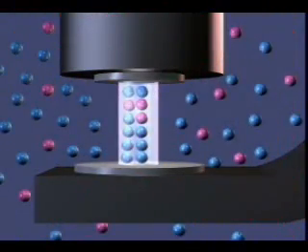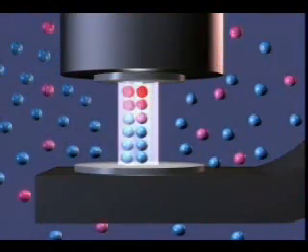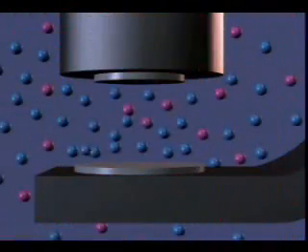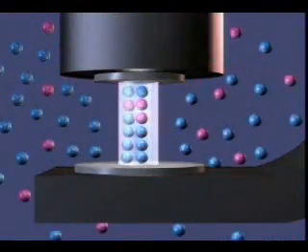The voltage applied to the spark plug has to overcome not only the resistance of the plug gap, but also the resistance created by the air-fuel molecules in the gap. When voltage is high enough to overcome this combined resistance, current flows through the air-fuel molecules. The current flow and atomic movement combine to create a heat path of approximately 30,000 degrees Fahrenheit, igniting the air-fuel mixture.